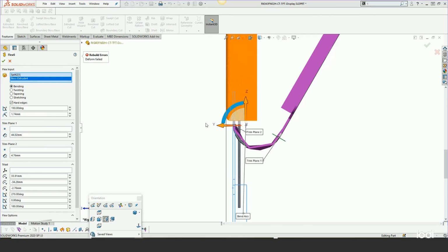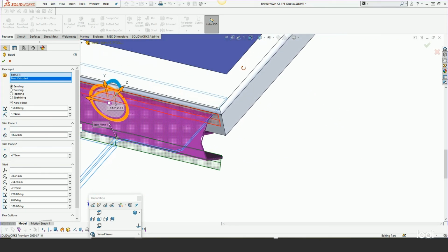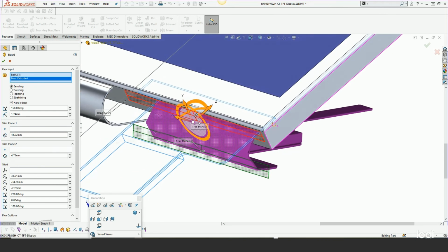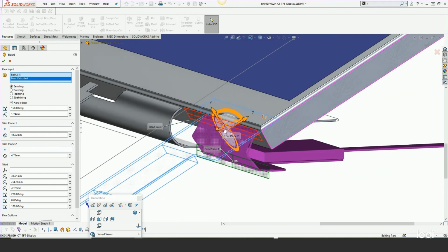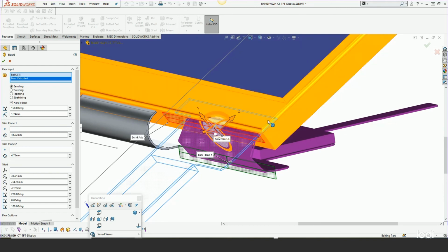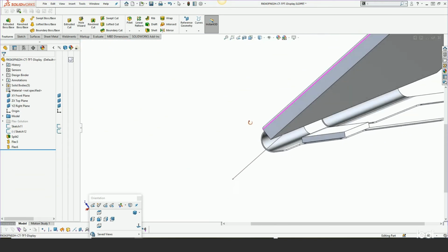And I'm glad this happened because this brings up another point. There are times when the deform of the flex feature cannot occur because it's going to create some invalid geometry. So a lot of times you can get around that. What it's trying to do is keep all the hard edges in the original topology. And I find that most times when you run into this problem where you get this error, deform failed, if you uncheck mark hard edges, a lot of times it'll actually solve. And that's the case in this.